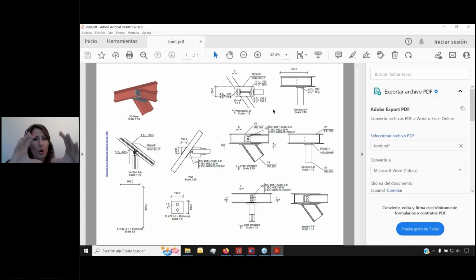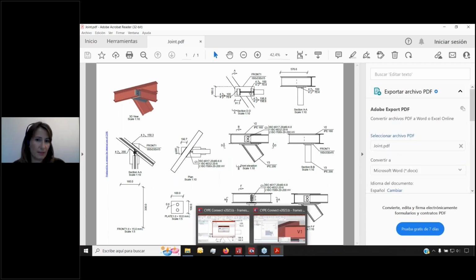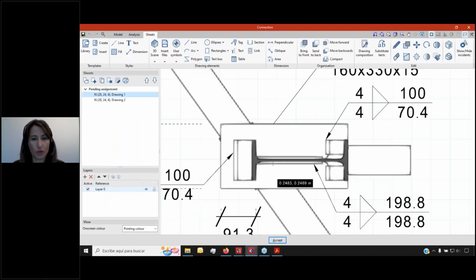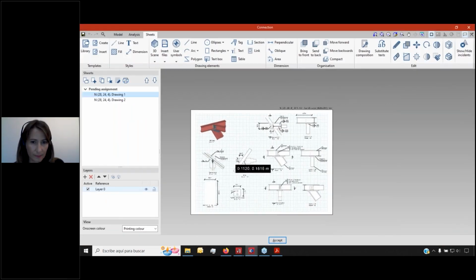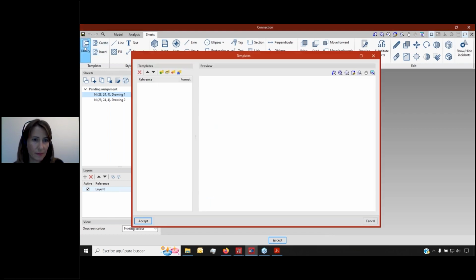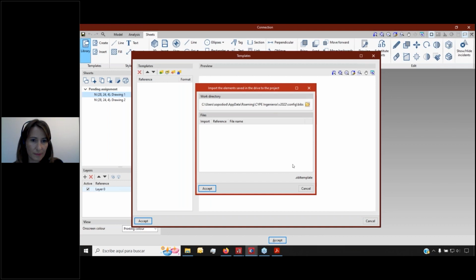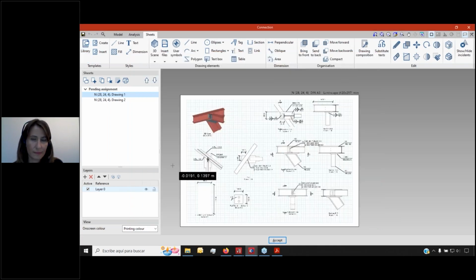And you can create your box with your details for your company and everything and save that, like creating a template for your drawings. Exactly. You can see here that we have that templates ribbon. And in the templates ribbon, you can manage your own library of templates. So in case you already have a template that you have generated with CYPE Connect, or even with OpenBIM Layout, which is our free tool for coordinated drawings based off of IFC files, you can reuse that data as well. So you can have your frame, your text, and so on all around your drawings.